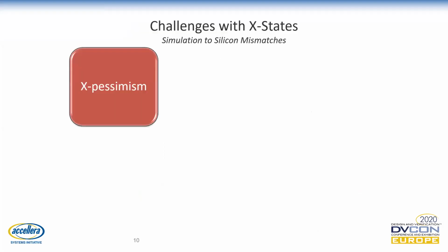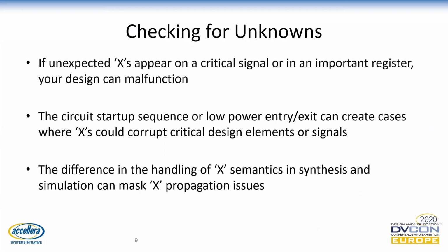Often designers don't focus on initialization and reset. Although sometimes, oftentimes FPGA hardware initializes at power up, but more advanced designs often now contain many resets and independent reset functions and domains. If RTL logic is uninitialized or corrupted, design signals would be at an unknown value or X value.